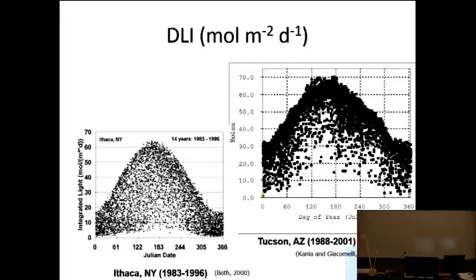Yeah, because right now you could have, just for number purposes, a 70% transmission shade curtain, but you're still going to have to deal with a high cooling capacity. If you lowered that to 60%, you wouldn't have as much temperature light coming in. And if you had supplemental lighting that's only operating at 30 degrees, that's not significant enough to really affect your temperature if you have a lower shade cloth. So you wouldn't have to cool as much. Yeah, interesting. TJ.